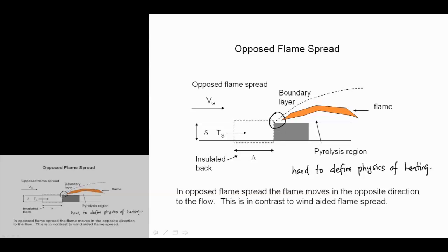One simple way that it's defined is this. The simple model is that at this edge, remember there's a quenching zone, and the region where the flame sits off of the wall is approximately the same region over which there's heating of the solid. So the model says that this quench distance is comparable to this heating distance.